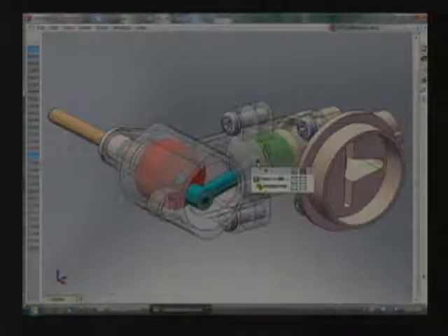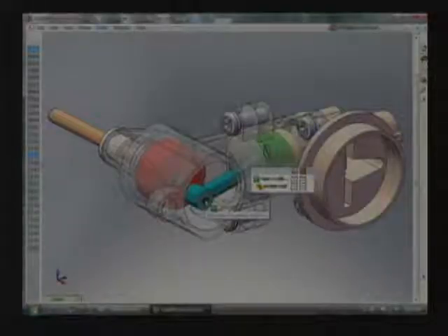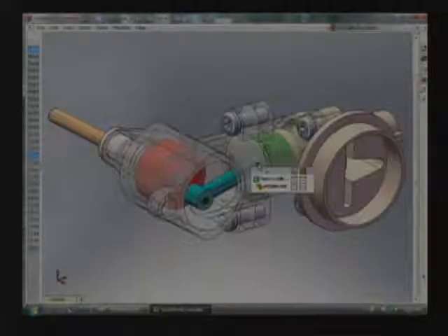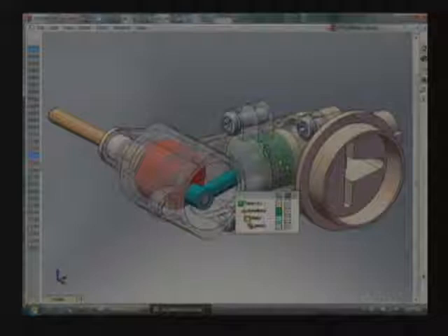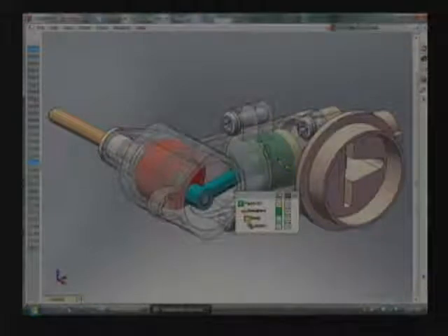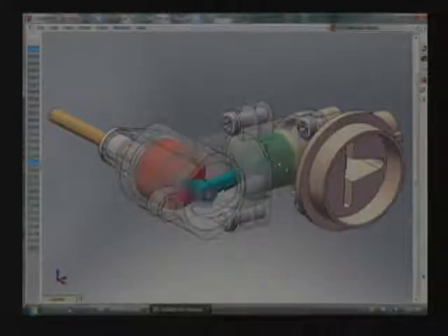Now again, the connecting rod is rigid, so the distance between the center of the crank pin and the center of this bearing over here that connects it to the piston is also a fixed length. Finally, we have the piston, which is in green. The piston is a cylinder, and it's inside of a hole that fits closely to that cylinder, so it can just slide back and forth.